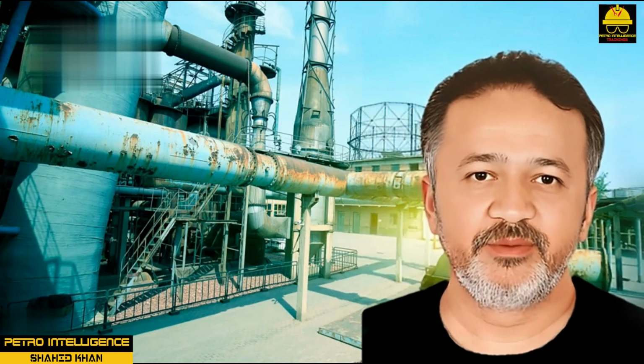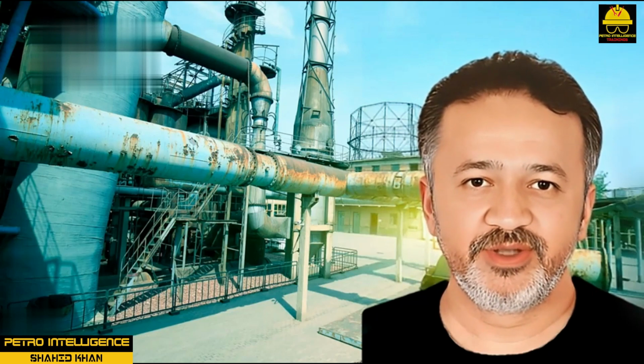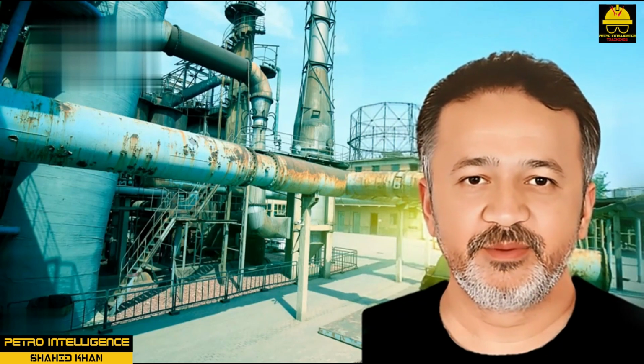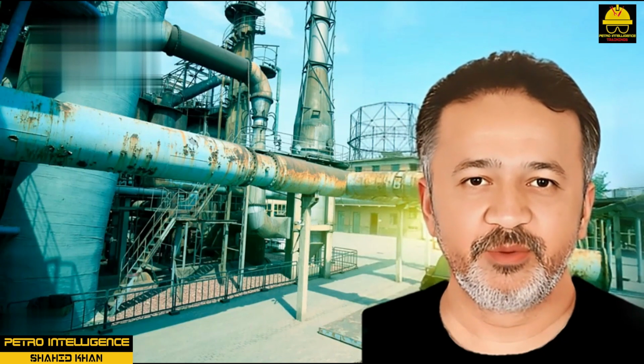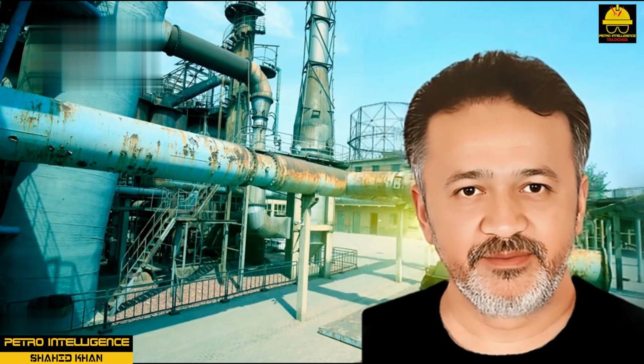Phosphate deposits are soft brown or gray and can easily be removed. Carbonate deposits are granular and porous. Sulfate deposits have a crystallized structure that forms a dense and very hard deposit. Silica deposits are very hard, with a fine crystallized structure that resembles porcelain. Iron deposits are characterized by a dark brown color. The primary problem associated with deposits is tube failure.